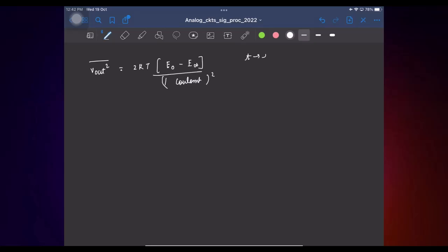Say, as t tends to infinity, in an RLC network you apply an impulse current. If you have to find the voltage as t tends to infinity, what will you do? Open circuit capacitors and short circuit inductors. Right? And why is that? We are finding the DC average value at that time. Actually, that's a fine point. We are not finding the average value, we are actually finding the total value. But being a passive RLC network, we know that if you apply an impulse, in steady state, voltages are going to be constant. So it is as if we are looking at only the DC portion.